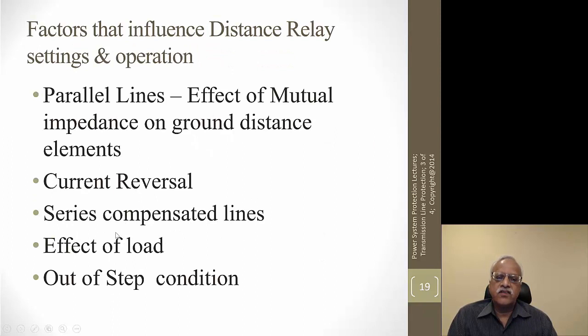The factors that influence distance relay operations, you can look at it. There are parallel lines, with the effect of mutual impedance to ground. Current reversals occur when there is a parallel line. As soon as one end of a line opens, the current reverses and tries to go on the other line. That might cause misoperation. Series compensated lines have special issues such as voltage inversion or current inversion.